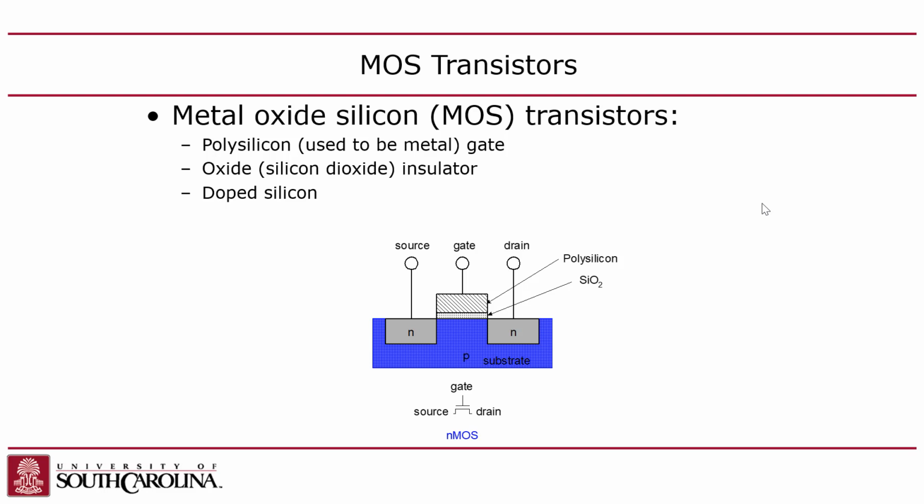And if you put a negative charge here, then you can attract the minority carriers out of an N silicon, right? If you make this negative instead of positive, and assuming this P is actually N, what does that mean, negative? Well, that basically means that instead of a 1 to turn it on, a 0 turns it on, essentially. But it's not really a 0, it's actually a negative voltage. But we think of it as a 0 because 0 is negative compared to the reference, right? If the reference is VDD and I put a 0 as the input, I'm actually putting negative VDD in here, which is putting a negative charge here, which will attract the minority carriers. So that's called a PMOS.